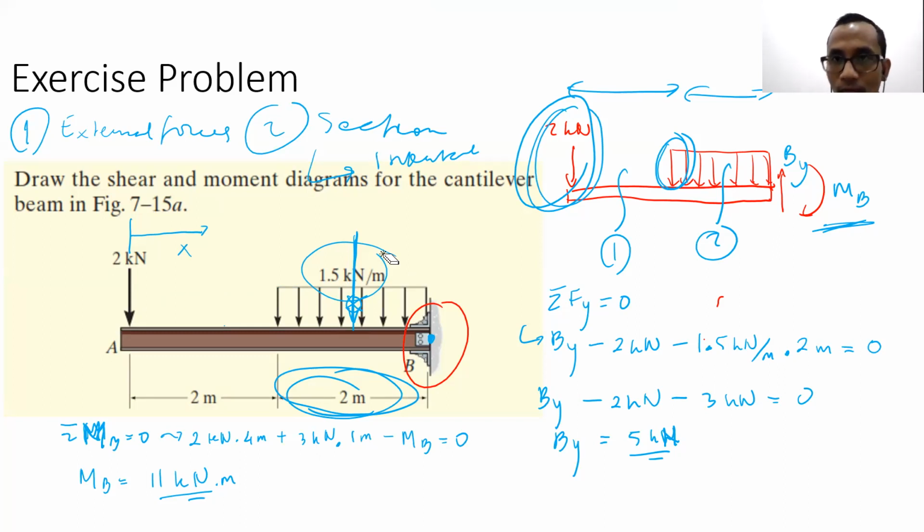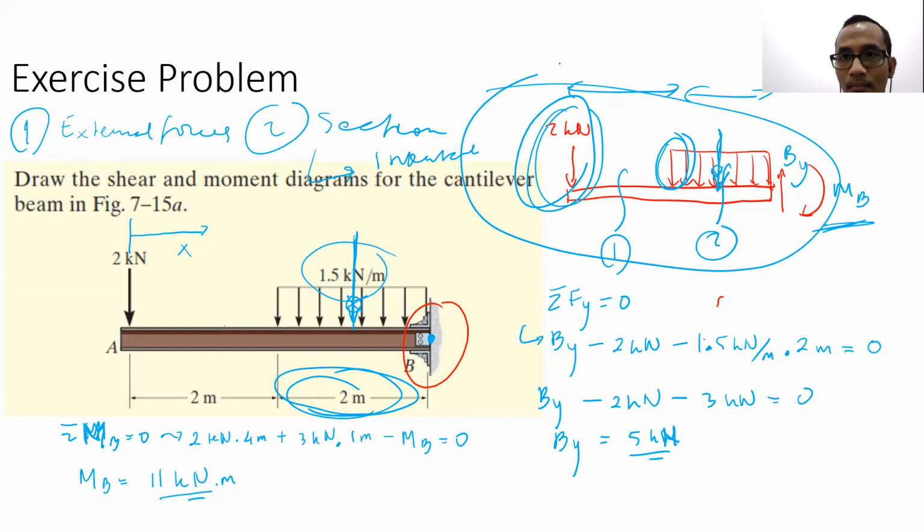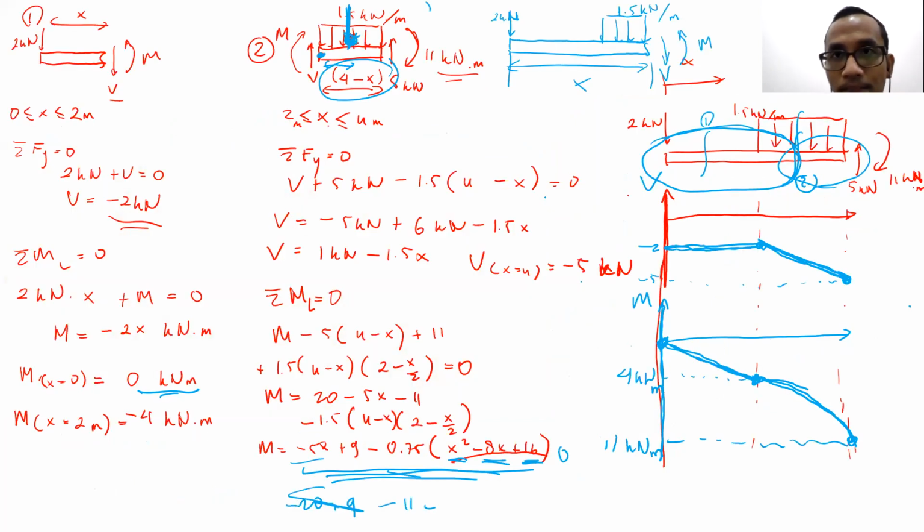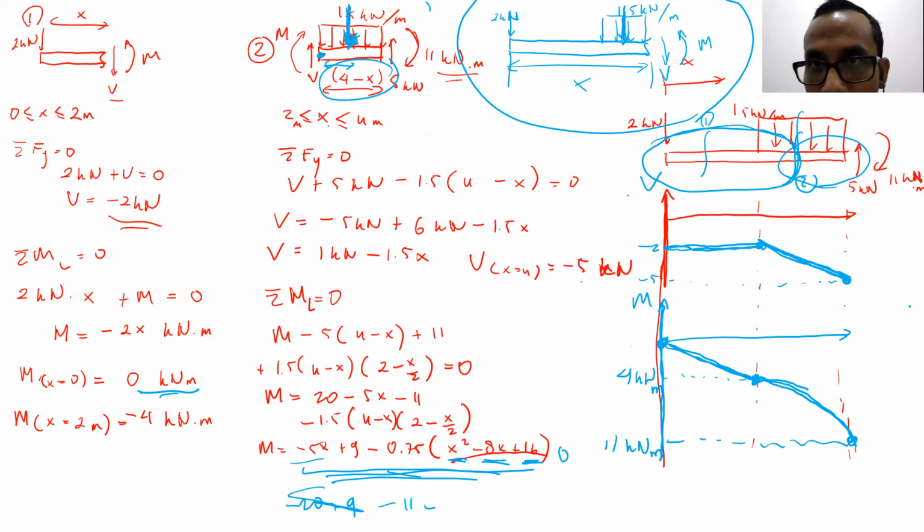Do you get it? So for example, if we have drawn this particular free body diagram, then we can assume that we have a concentrated load at its centroid like this, but it's just for this particular free body diagram. It will not be applied for other free body diagrams. So another example is like this. Okay, I want to use this particular free body diagram. Okay, for this particular thing, then this is my representative concentrated load at the centroid.